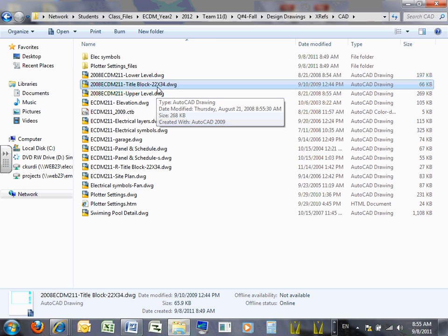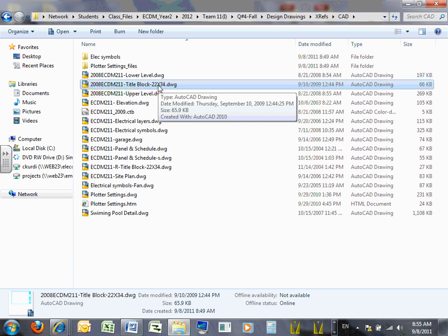Chad, just a question about the title block. Yeah. So we can edit later on. Yes, title block, yes. And put in symbols. Absolutely. That's why I don't want you to get hung up on how the title block looks now, because when we do CAD, guys, you're going to see in a second here, there are 3 files to make a drawing, 3 files. One of them is the file that you're working in. The other 2 files: one file will be for the background, we call it the background. We XREF it. And the second file is the title block. These 3 files together make a piece of paper that we print, that 22 by 34.